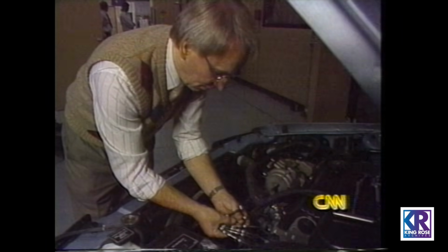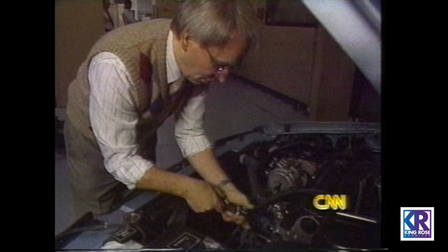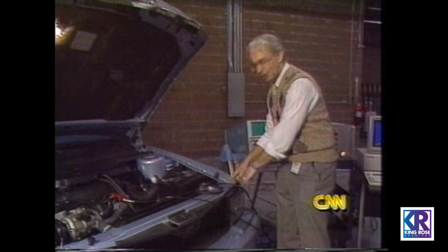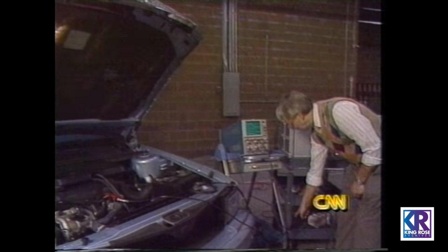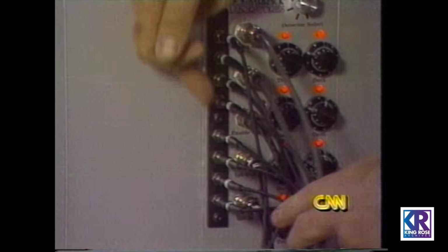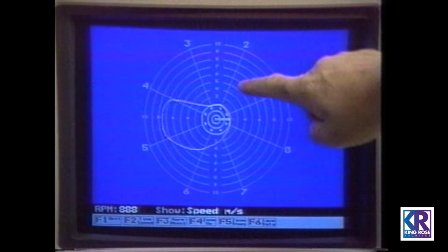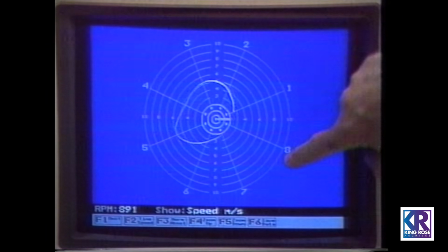The spark plug probe replaces a regular spark plug. The blue wires you see are the fiber optic cables. They run from the spark plug probe to an electrical box, where the optics light signal changes to an electrical signal. That leads to this computerized picture of the actual flame inside the car's fiery combustion chamber each time the car ignites.